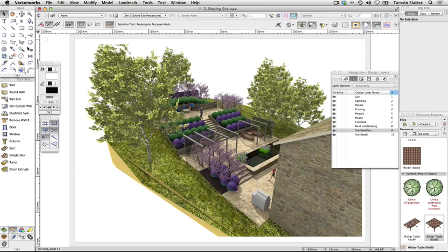The key to creating a successful site model is to have accurate height data. This could be information that you derive from your own survey, an imported survey, or it could be the spot heights or contours that you've determined as part of your design process. Create a simple slope. A site model can be created from stakes or loci that represent individual height measurements. Alternatively, it can be created from 3D polygons that represent contours. In this exercise, you'll create a simple slope from stakes representing individual level measurements.